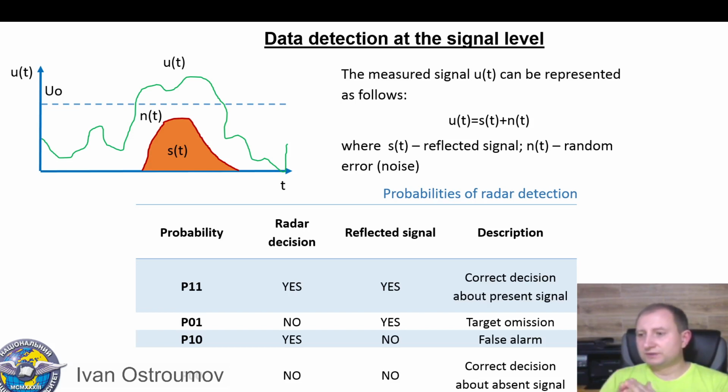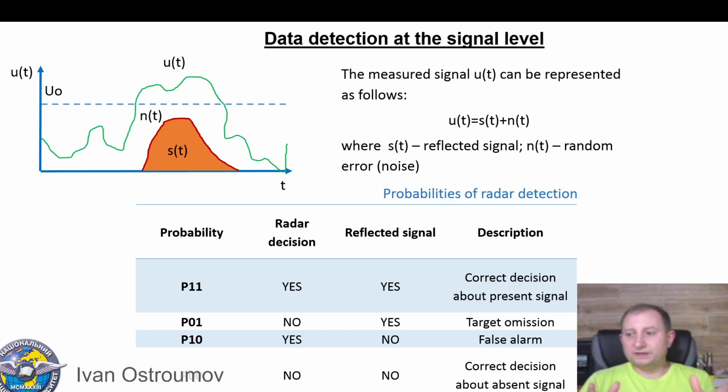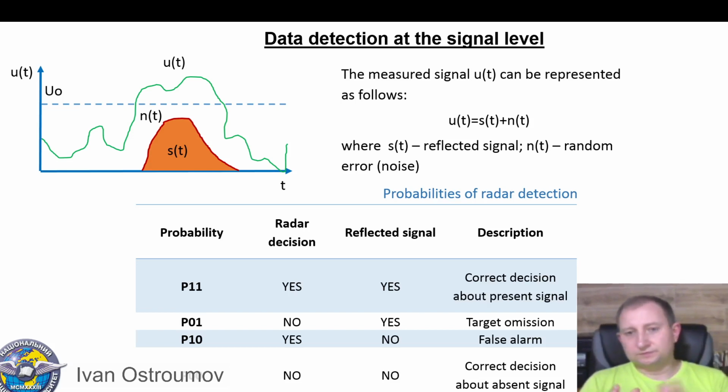The main idea of radar operation means that we've got a transmitter with a directed antenna, and this transmitter can generate a specific radio pulse and then apply this radio pulse to the antenna. Then this signal will be radiated from the antenna element and will propagate in the airspace. Due to directional characteristic of this antenna system, we can transmit signal directed at some particular direction.